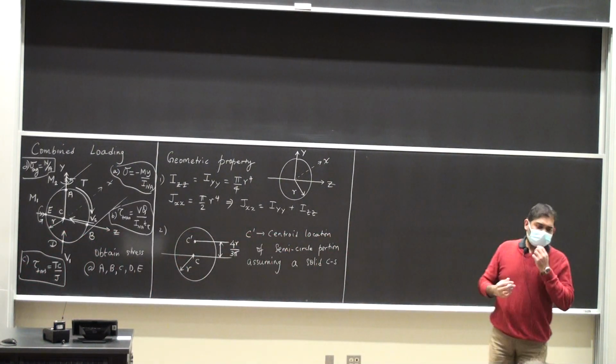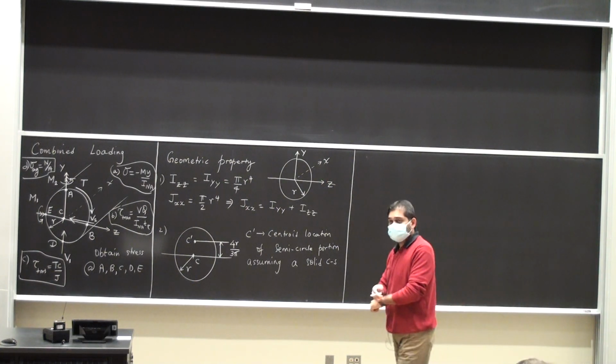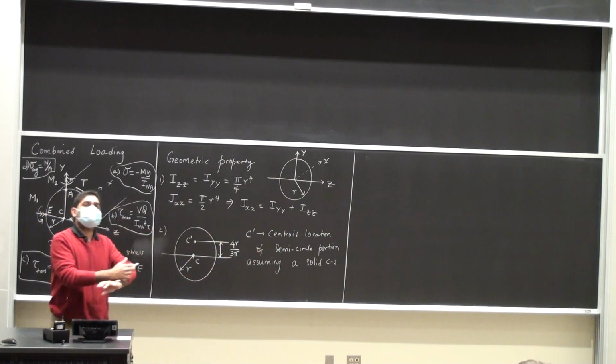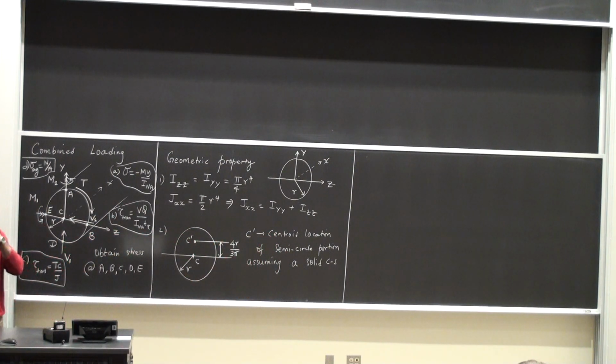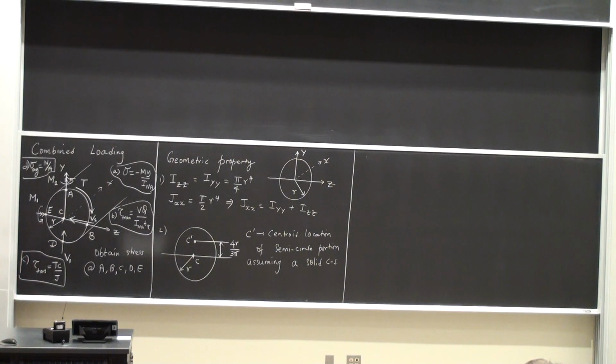We also had looked at the average shear stress a long time back when we started the ME 2020 class, right? Which is tau average is V divided by A, the shear force by the area of cross section. It is typically not used. Then the obvious question is, why did we teach this? It is the simplest formula to estimate shear stress as an average. But the more correct way of calculating transverse shear stress is using this formula. Alright.